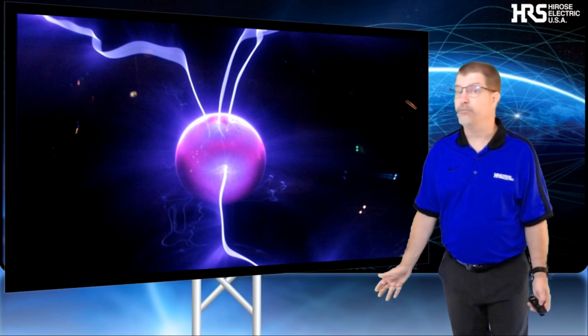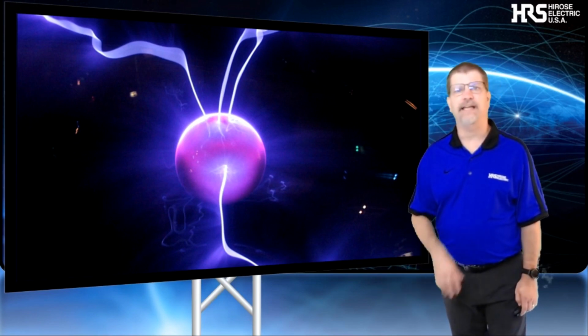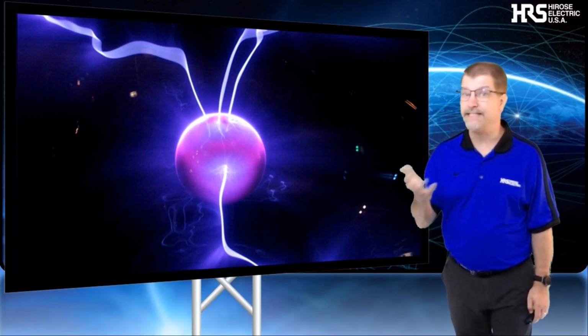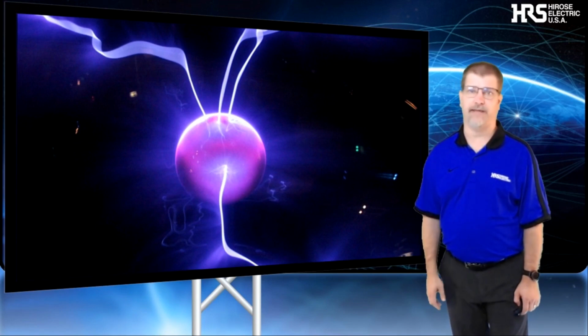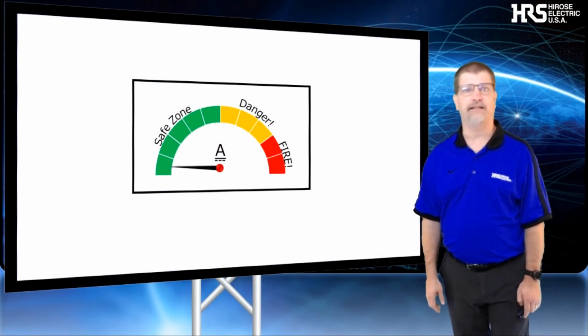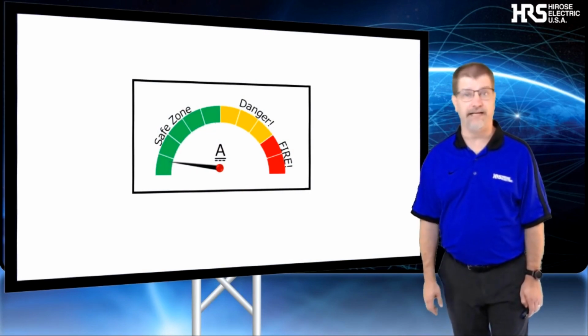Are you running current over more than one contact, maybe multiple circuits? Are you dividing a higher current need across more than one contact, but it's only a single circuit? For power connectors, we need to understand that application and how that current will be distributed across the connector. If your current is running over a single contact, then this rating is simple and listed in the datasheets.